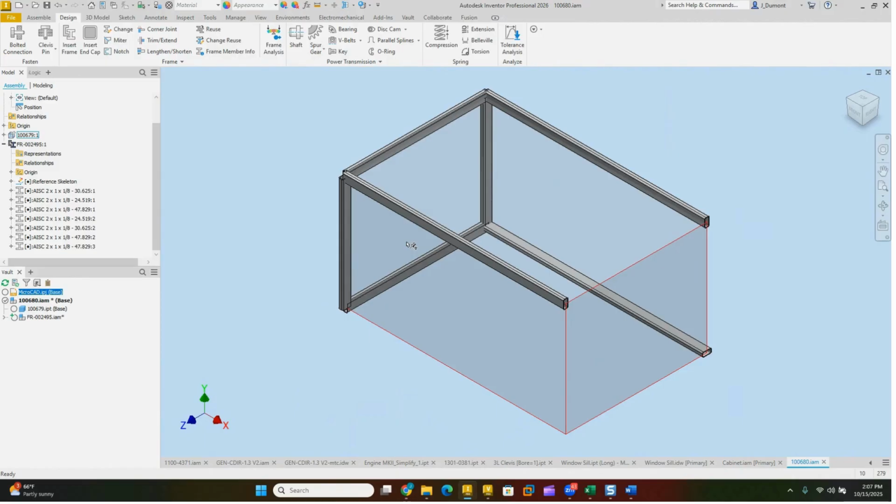down. A lot of times you open up Inventor, hey, found the file here, but now I find it here. Is this the right one? So those file resolutions, if you have the same name in different folders, it can get confused. You can open the wrong file in the wrong path. You think you have the right one. It's really important to understand what files are coming from where, that your assemblies are clean. So it's best practice. You don't have to have it on.